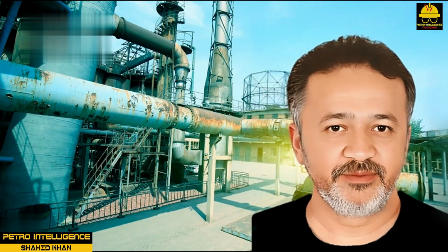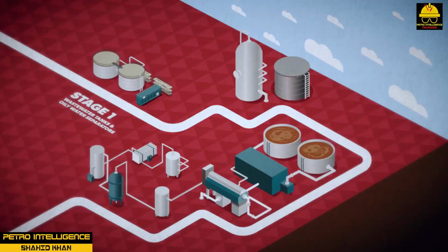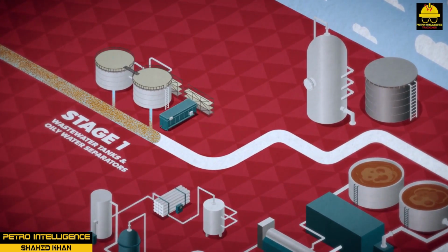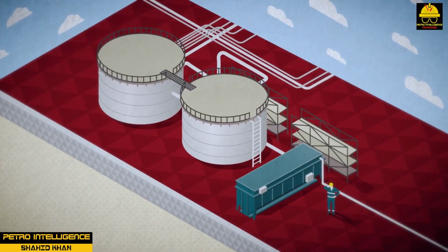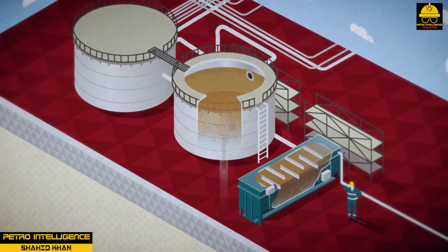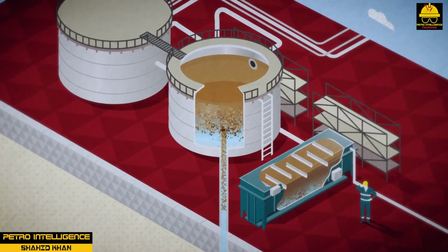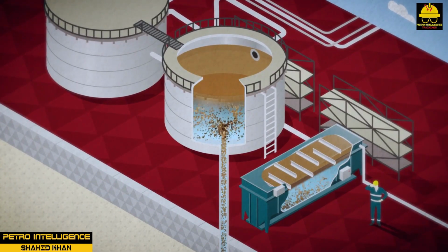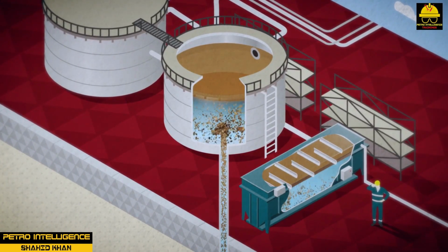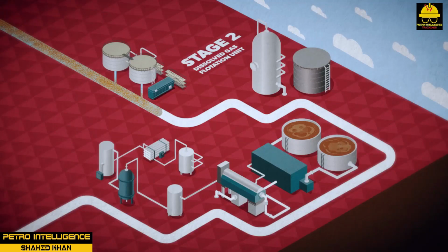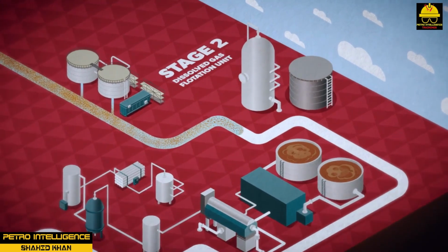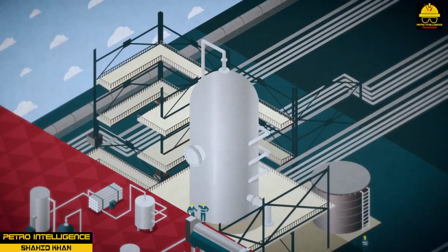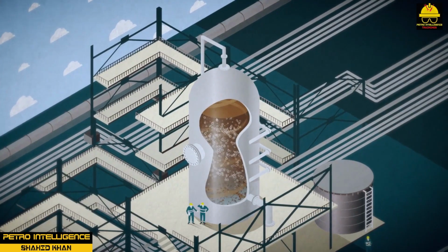Industrial sewer system. A plant sewer system collects all drains, water and process fluids, from the process units. All water is collected in a series of ditches and routed to the plant waste treatment area. Units that have hydrocarbons that will remain in the liquid phase at ambient temperatures have an American Petroleum Institute (API) separator, which separates the oil phase from the water phase before routing the water to the plant sewer system. Removed oil is rerun or used for fuel.